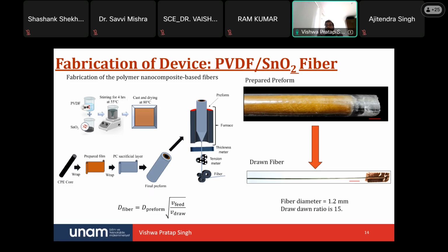So we get the viscoelastic analysis of this. I will show those plots in further slides. When you do those, you calculate the storage modulus as well as the loss modulus. We measure the storage modulus from minus 50 to 50 degrees Celsius for every material.